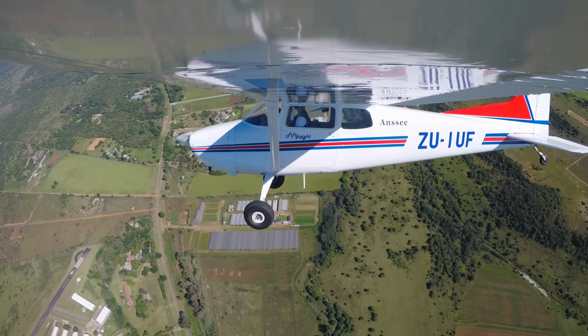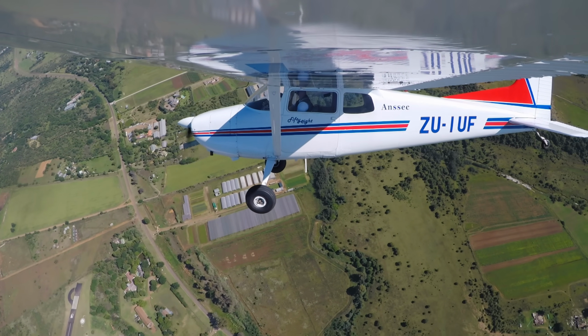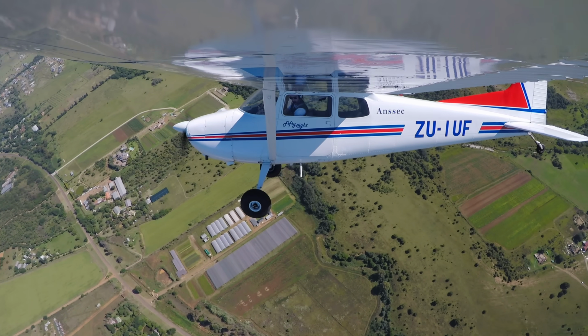This is why it is taught that bank angle increases stall speed, even though bank angle itself has zero effect on stall speed. It is only when it's required to maintain altitude that bank angle will increase stall speed, which is due to increased load on the wing. You might ask, but isn't maintaining altitude the norm when turning an airplane? And that's a fair question, as it is the norm to control vertical speed while turning.